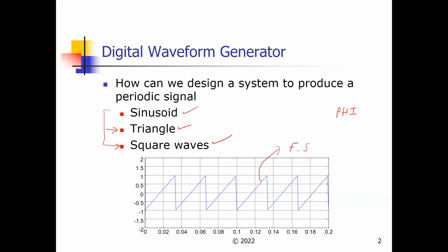These are all done, remember, by a processor. So you can generate as many harmonics as you want, as many as possible, right? Typically, to get a good ramp or a good square wave and so on, you probably have to generate like 15 to 20 harmonics. But it's a simple thing.